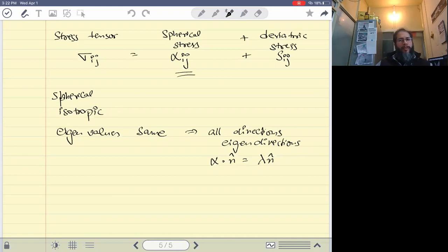Now, if I again ask you that think of some second order tensor for which all eigenvalues are the same, then there's no other tensor which is other than some scalar component of the Kronecker delta. Remember when we said that Kronecker delta is the only isotropic second order tensor. Okay. Whatever orthogonal transformation you do, it stays the same.